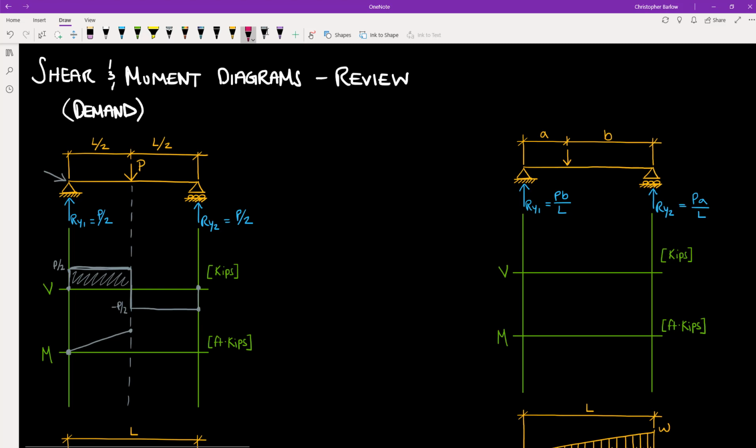So to help you visualize that, if we took this location here and calculated that area, we would end up somewhere along the curve here. Then if we moved further to the right and calculate the area that we've accumulated up until that point, we will have a little more. And that continues until we reach this maximum point at the midspan, where the edge of our rectangle occurs.